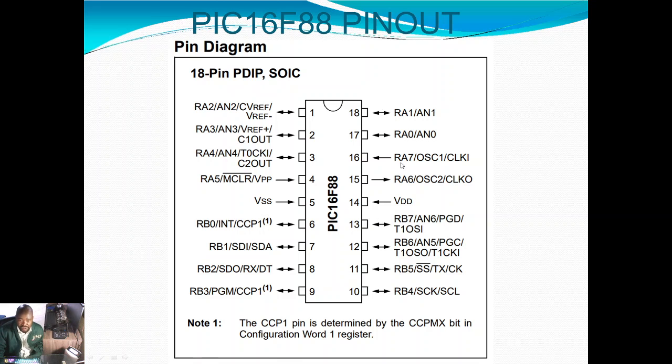You never connect an output to RA5, right? Other things to note is that most of port A pins come with analog capabilities. RA0 to RA4, they have analog capabilities, and also B6 and B7 have analog capabilities. This PIC microcontroller, on default, it comes with analogs enabled. On default, these PICs, which have ADC capability, are on default analog pins.